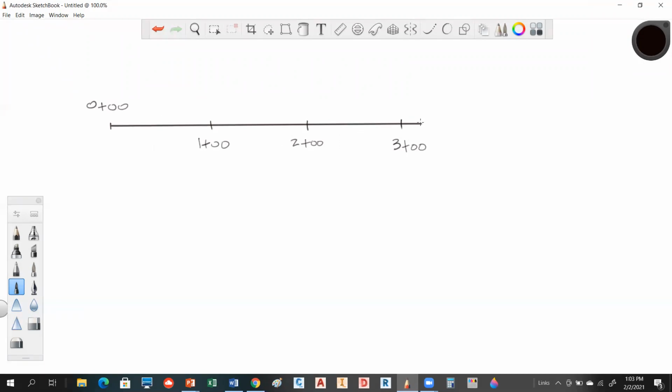Notice which way this is traveling. This is traveling in that direction. So if you put yourself at 0 and you look the way it's going, this is the left side and this is the right side of that alignment, which is important because if I come to this point right here and I measure this distance, let's say that is 1 plus 70, then I have to know whether I'm left of the alignment or right of the alignment.